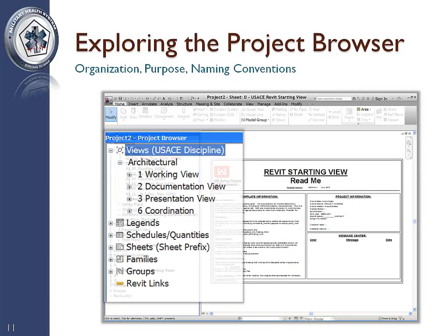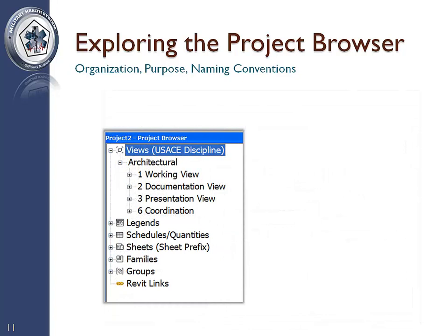On the left side of the Revit user interface is the Project Browser window. Within it, you can browse some of the custom views provided by the template. The Project Browser is organized by discipline, view purpose, family and type, and sorted by associated level. View purpose is a new project parameter added to the view properties by the template. The uppercase view designation is appended to the end of the view name. Four predefined view purposes have been created in the template.